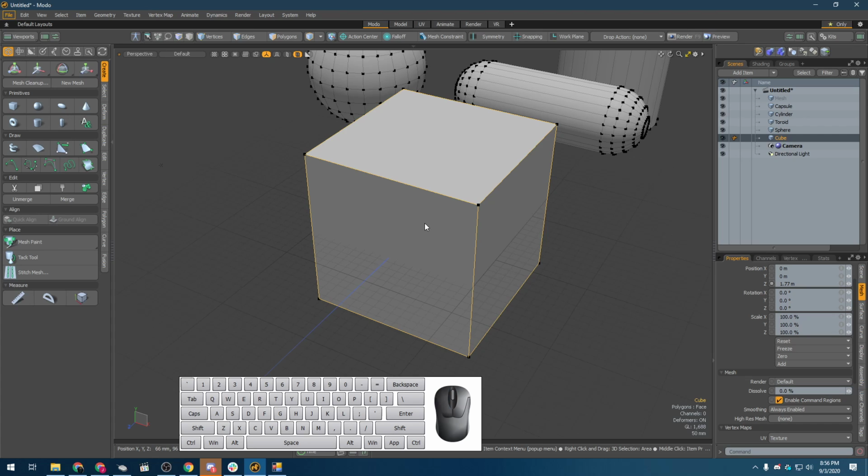The next thing I want to talk about is some of the other options in this transform manipulator. So first of all, if I hit the plus button, which is also the equal button, right, on the keyboard over here, it's going to grow or shrink that transform manipulator. So if it's too small and you can't really hold the controls or click on them, you can just press the plus key to grow that out.